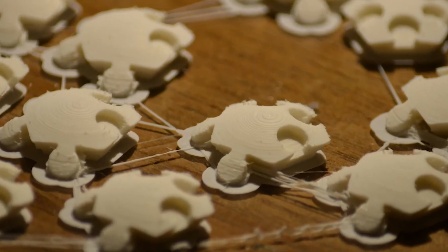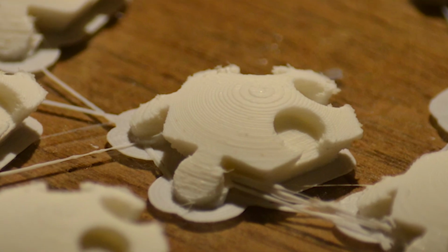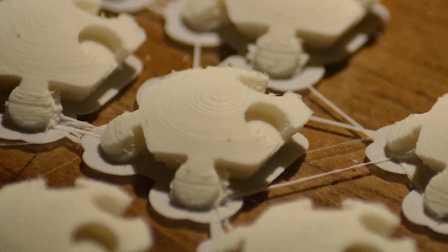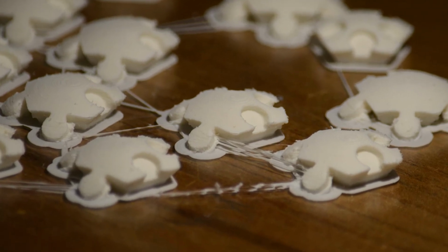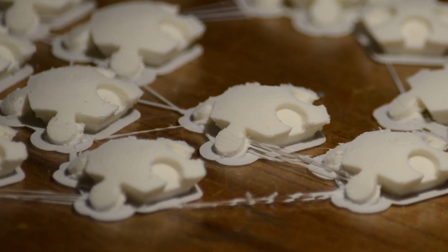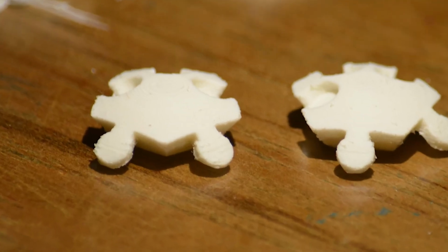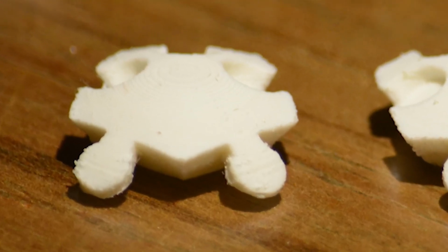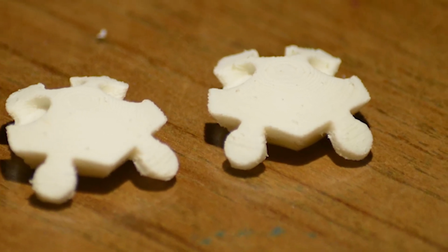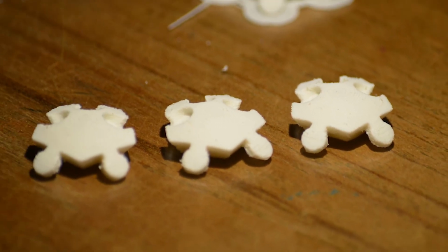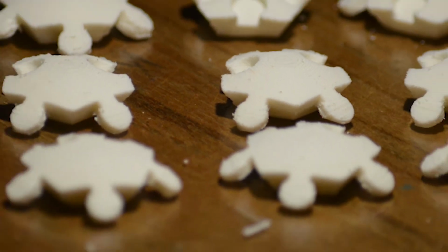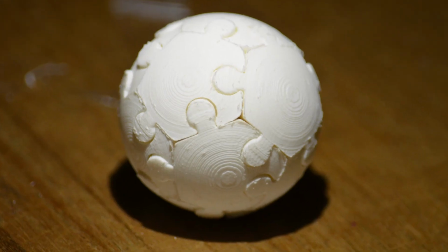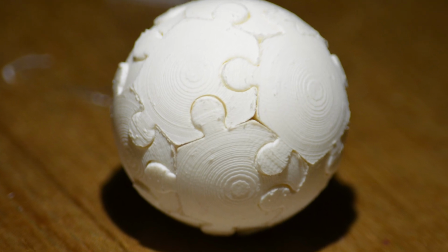Now the print job is finished. I took the glass plate with the print and moved it to my desk. Here I am showing you stills from the result. I've zoomed in as much as I can so that you can see the quality of the print. As you can see, there is a lot of stringing going on in this print. In this case it doesn't matter so much because I will need to cut away all the support material anyway. In another case it wouldn't be nice to have stringing, and then I had to adjust that.